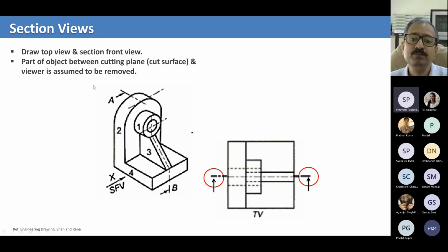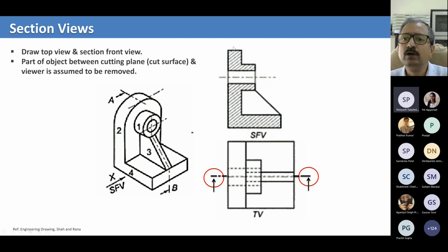Front view, how should it look? It should look like an L shape, right? If you see the front view, an L shape all the way to this height. And then you see this projection of the boss and an inclined rib, which I talked about. But a cross-section through the entire vertical plane, perpendicular to the horizontal base. I talked about this whole thing. L shape is this L shape, and then you have this rib here.